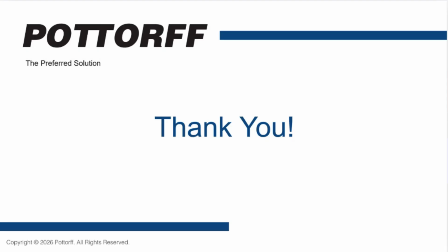Sometimes across certain manufacturers, you might even have the same bird screen, and one has a higher free area, yet somehow a lower pressure drop. See if you can actually argue that the louver with the lower pressure drop should be the one that is selected.